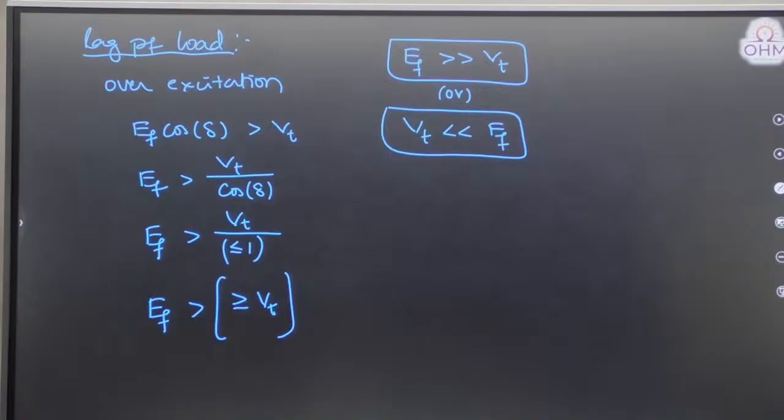Right. Yes, zero voltage regulation is possible only for leading power factor. That is correct. Maximum voltage regulation is possible only for lagging. Correct. Yes, condition for maximum reluctance power: reluctance power will be maximum when delta is 45 degrees. That we will see in the salient pole machine. We have not yet come to that part. We call it two reaction theory. That I will cover in the third part of synchronous machines.